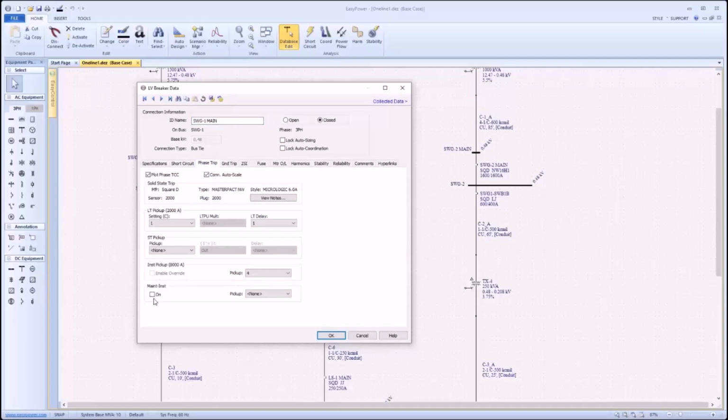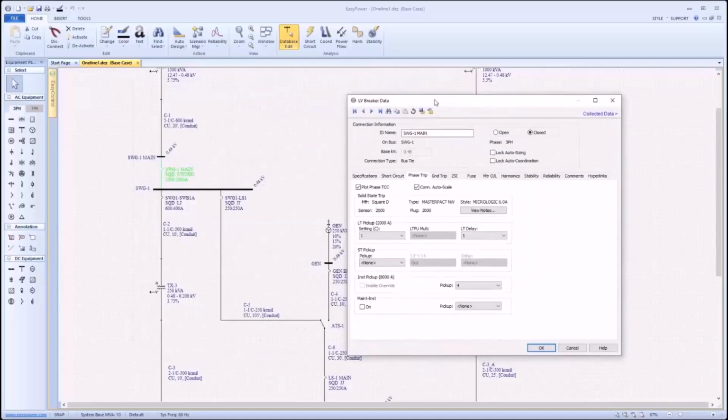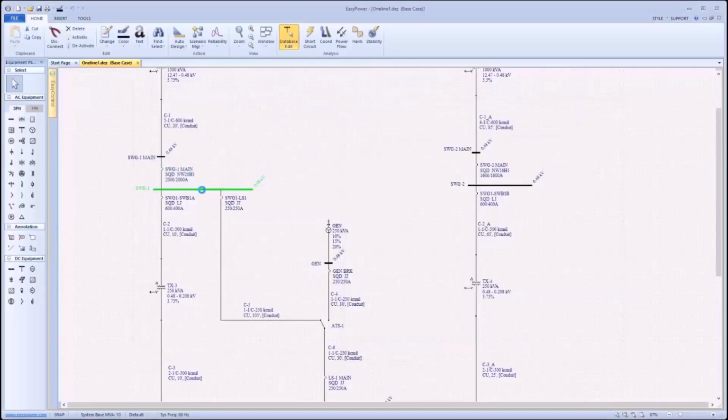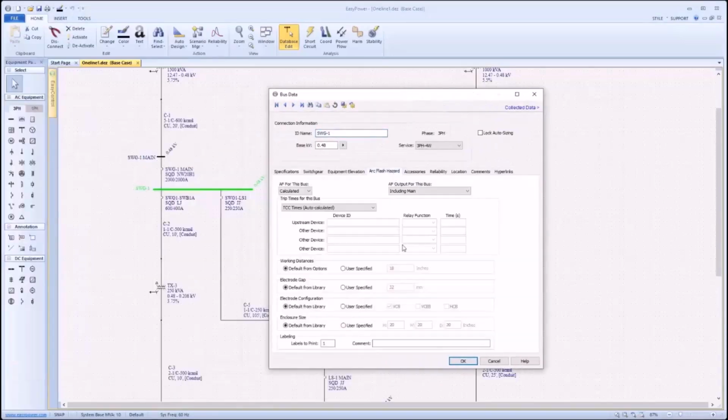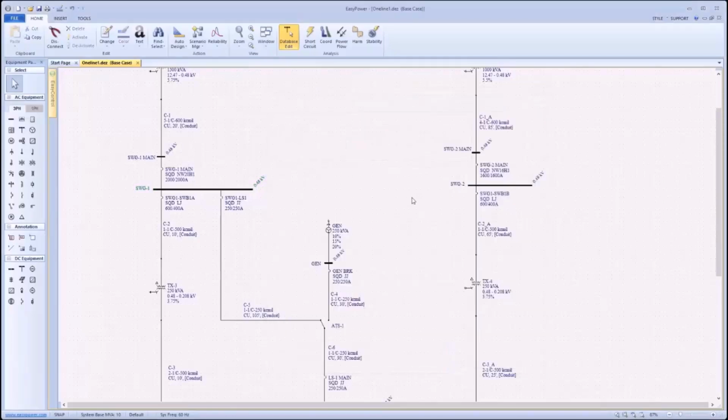So presumably I might like to generate an arc flash table perhaps for a customer with separate results with maintenance settings on, right? This breaker here I have set up, I'll show you here, to trip for this bus here, assuming that breaker is isolated, so it's got including mains. This breaker will actually trip for arc flash. Both of these will. So I'd like to set up a couple scenarios for maintenance settings.